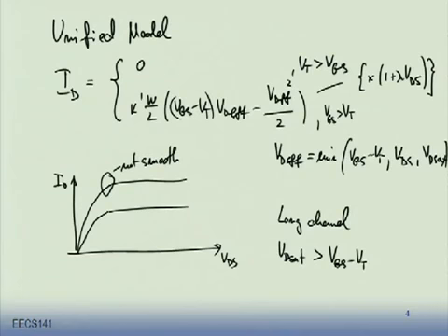Now, just keep one thing in mind. Short channel devices really don't have that saturation. Everything is velocity saturated. We did it for the modeling reasons. Otherwise, we would have had a badly discontinuous model.